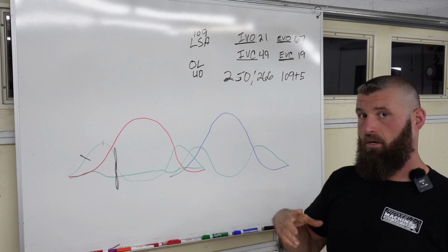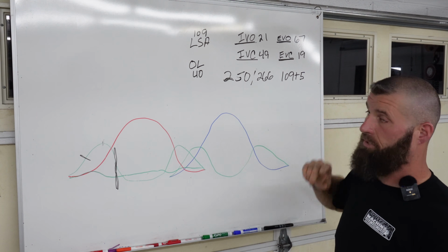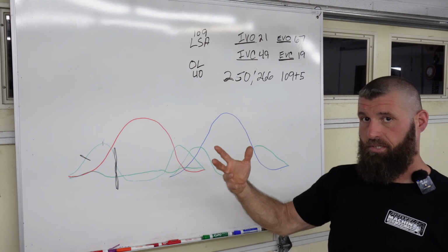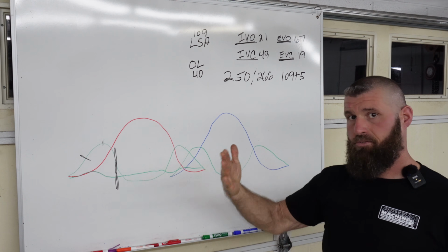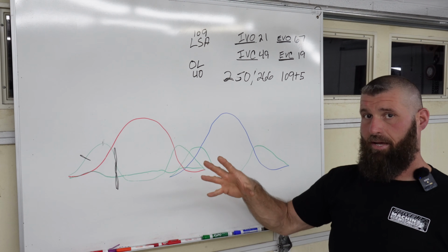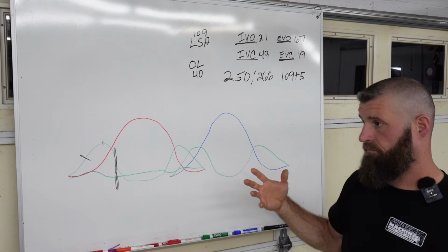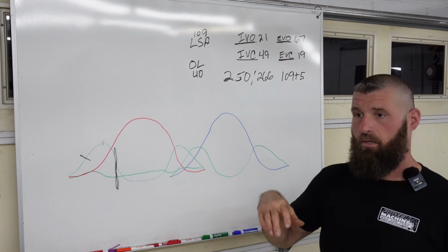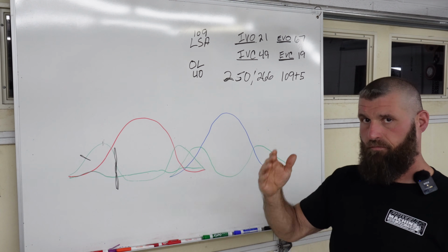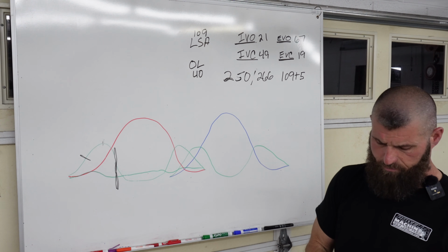And then because of more RPM, we need to open the exhaust valve a little sooner so we can start evacuating the cylinder a little faster, because the faster you go, the harder it is for pumping losses, because there's just less time to move the gases in and out of the system. And conversely, generally speaking, and again, it's just application relative, but a little more overlap is friendly for more RPM also. So I think, let me get the numbers in front of me so I don't tell you a lie.